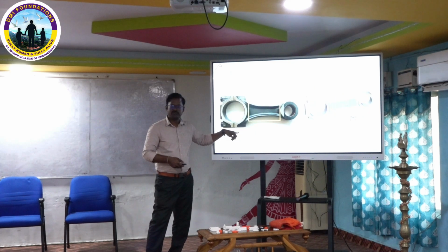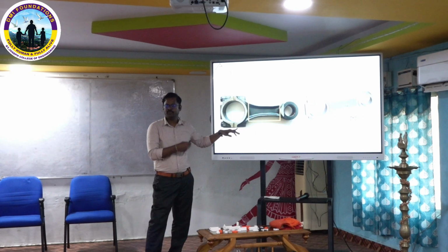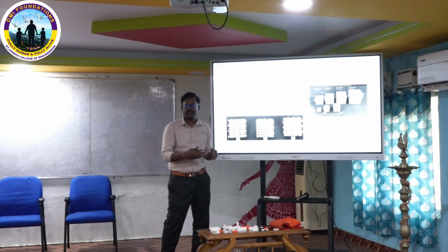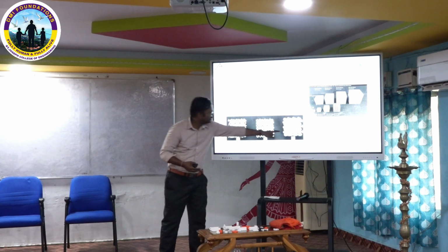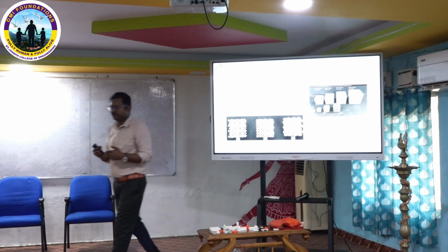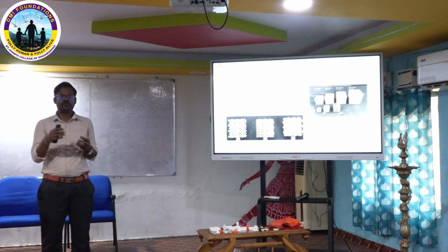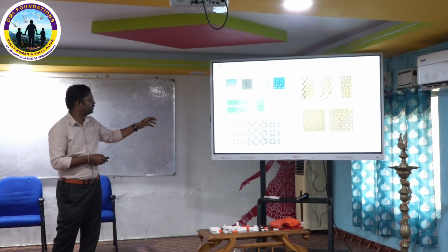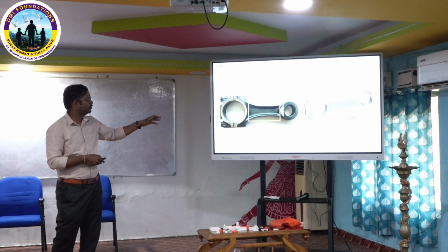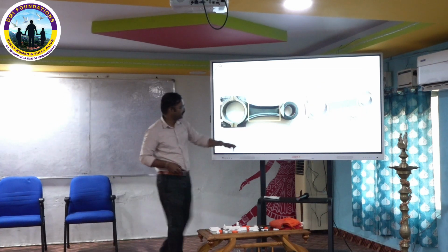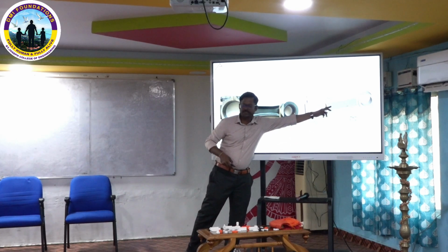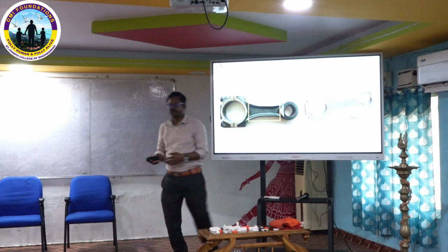I can see more of the whites here, so I can easily remove the unsintered powder. But when the density or dimension increases, the voids get closed. So what will happen? The removal of powder is more difficult, especially when I incorporate parts into this lattice structure. I can easily remove the powder from the center, but in the corners I can't.